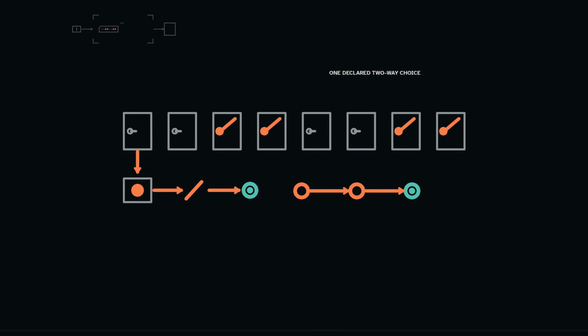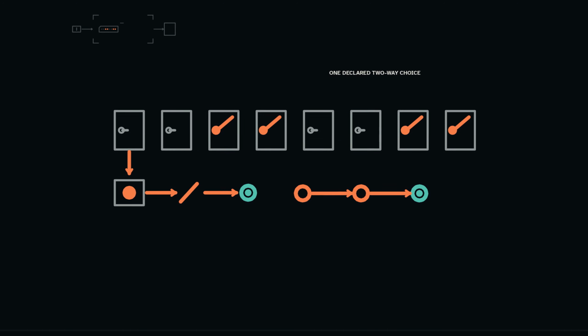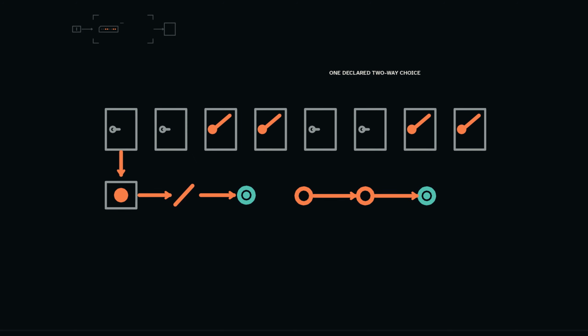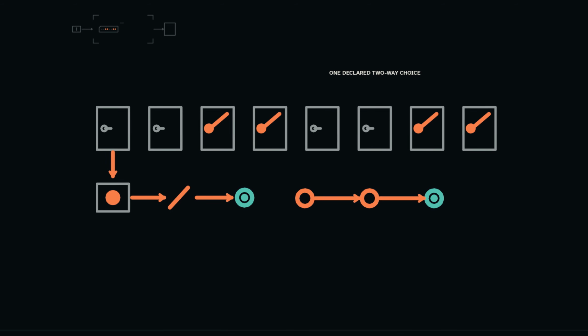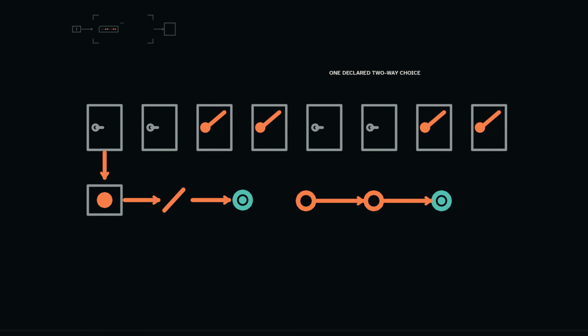Keep 3 ideas separate. The carrier is the physical thing or measurable condition. The encoding rule assigns values to allowed states. The value is the abstract 0 or 1 that later logic uses. These are connected, not synonymous. Calling a wire a bit is loose speech. More precisely, the wire carries a condition from which a receiver recovers a bit value.